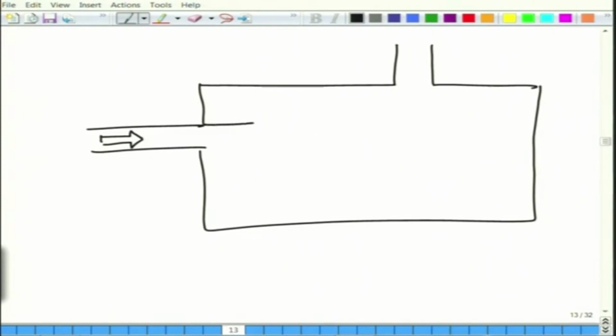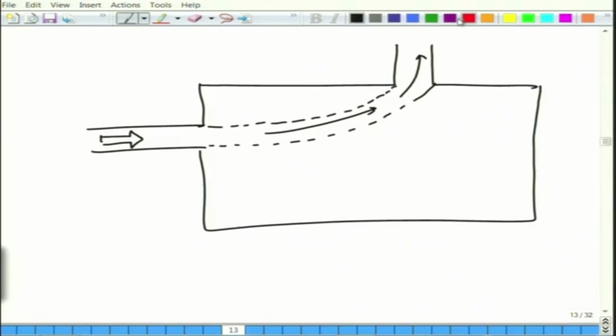So, one good practice is to have some kind of a bend which connects gradually, and what we actually do is have some sort of a perforated surface all throughout. So, this entire cavity then is accessible. So, the flow is nicely, smoothly guided from the inlet and outlet, and the waves are able to go through the cavity here and interact. This is like a quarter wave resonator, this is your expansion chamber kind of behavior, and similar logic would probably apply for your side inlet and side outlet chamber.